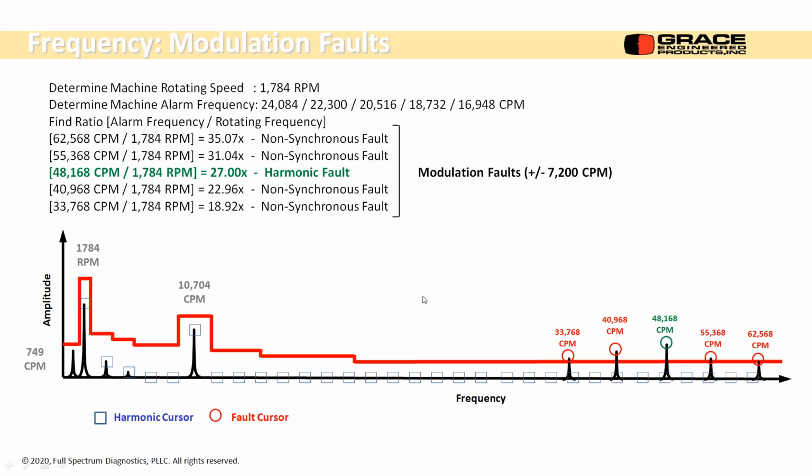Okay, you don't really need to diagnose it to that extent. I'm just trying to give you an idea that there's a center frequency and there's a spacing on the sidebands, and the spacing's telling you the source, and how it's modulating. So that's one type of modulation fault.